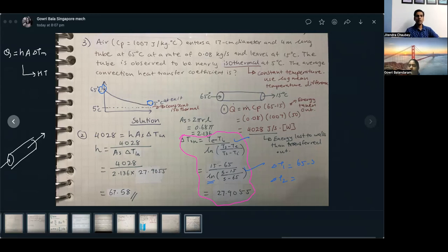See, this is the heat transfer rate, the heat flow rate. It means it is the heat absorbed by the fluid per unit time. And then another formula is Q is equal to mCp dT. This formula is called the formula of heat storage, or heat capacity, or heat gained or heat lost. This formula comes from the definition of specific heat.